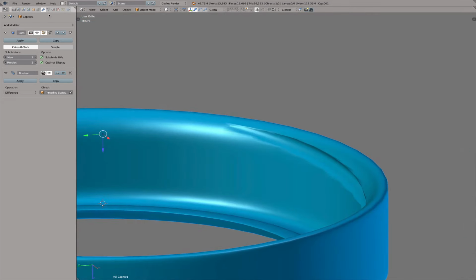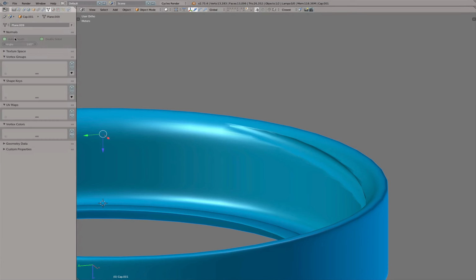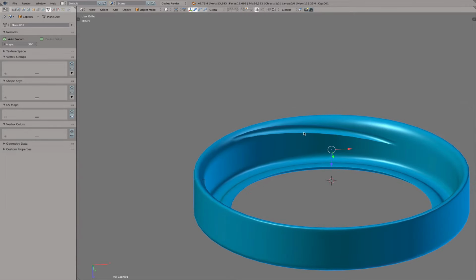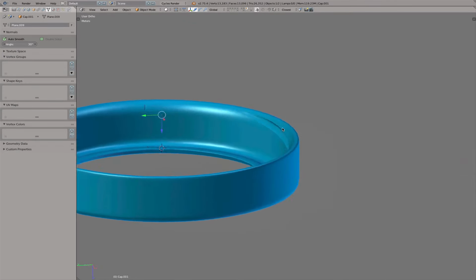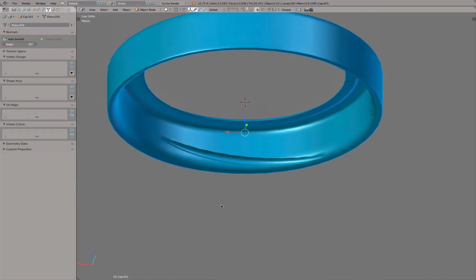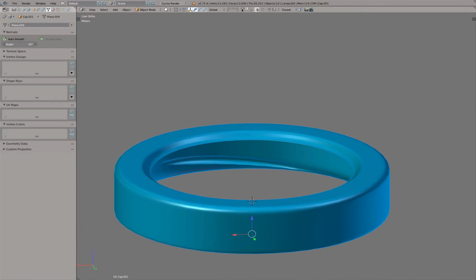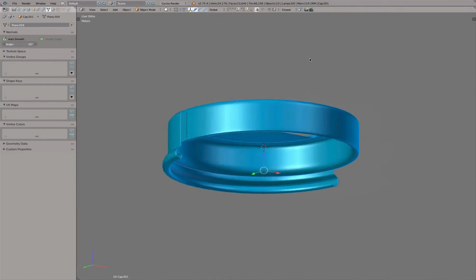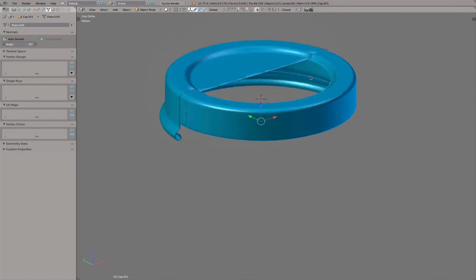A little bit softer. I would like to have maybe a little bit crisper edges, so I could go to the mesh information and say auto smooth, maybe 30 degrees. Yeah, okay, and you see like those edges are a tick sharper. Perfect. Yeah, let's actually take a look at this with the cap. So that actually should work pretty well.